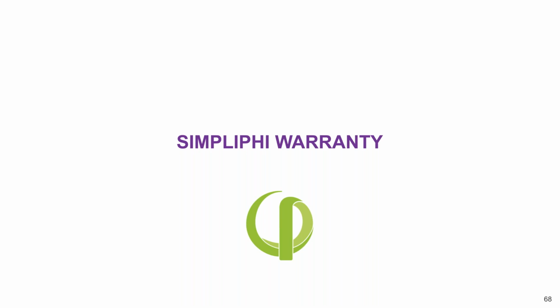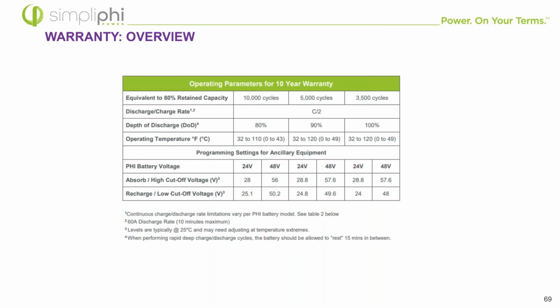Okay, as far as warranty, I think we've beat it up already, so we all have an understanding. If you're looking for anything, go to our warranty itself. You'll find tables like this that go over various parameters, even voltage set points that fall in line with things like 80% depth of discharge. So, you can see here 50.2 called out in the warranty as how low you want to discharge the battery to hit that 80% depth of discharge.